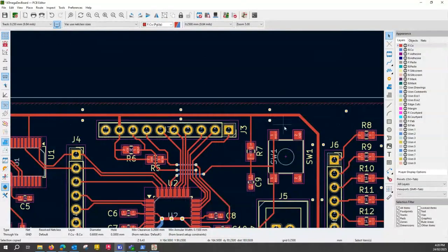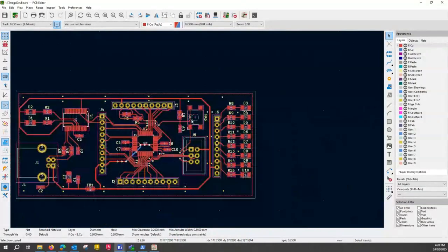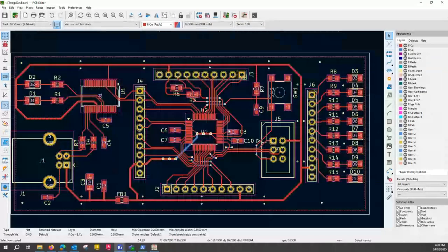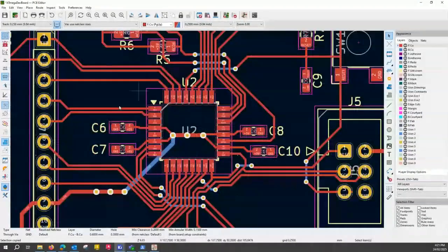Okay. Now, so this is my basics. I go around. The second lot I want to put in is close to my microprocessor. So I'll put one in every corner. This is what I always do, making sure that those ground planes are connected.